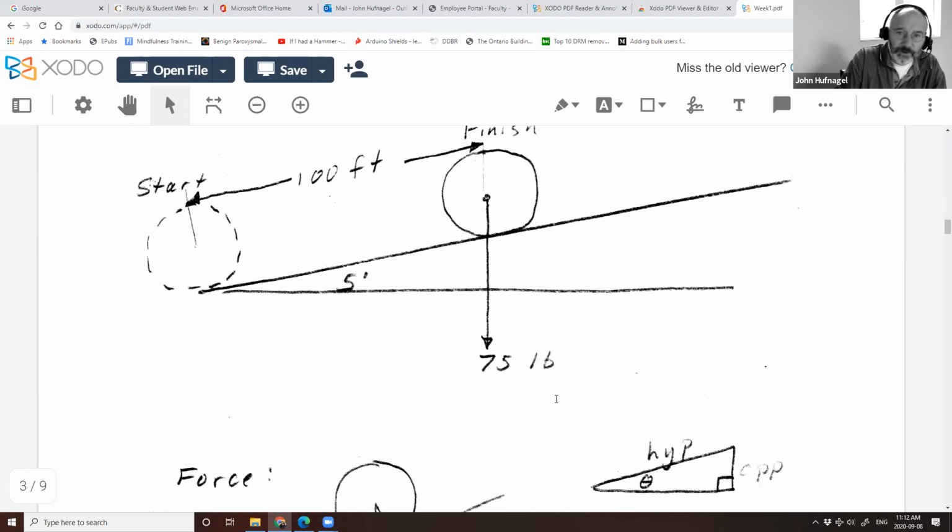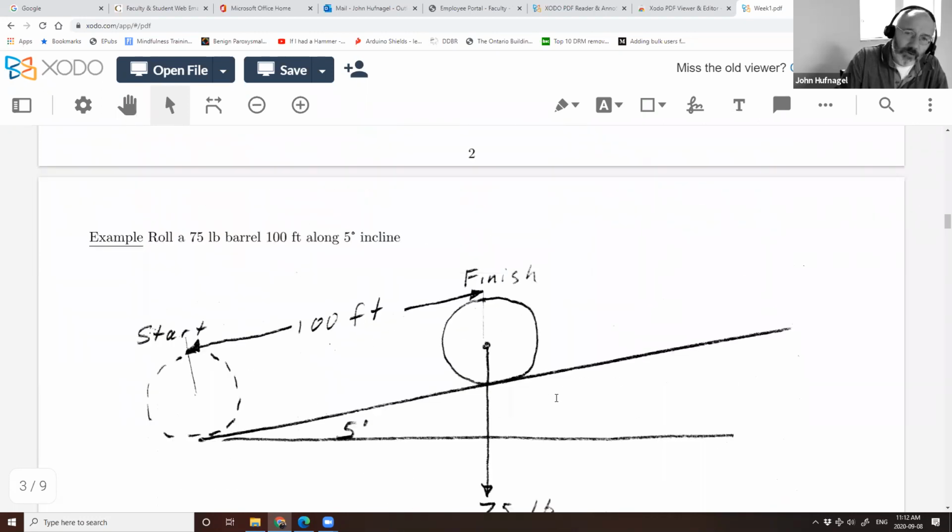So going back to that old one, when you're rolling, you're not creating friction. Well, actually, you sort of want some friction on there so that the thing doesn't slide, especially if you're walking up this thing. But friction is not causing a loss of energy because you're rolling and you're not fighting against that friction. You're not rubbing against the friction. It's the rubbing against the friction that would cause the loss of energy.